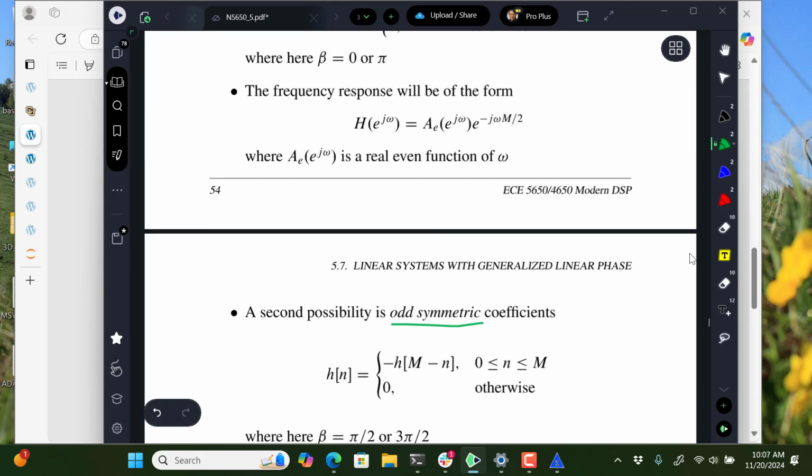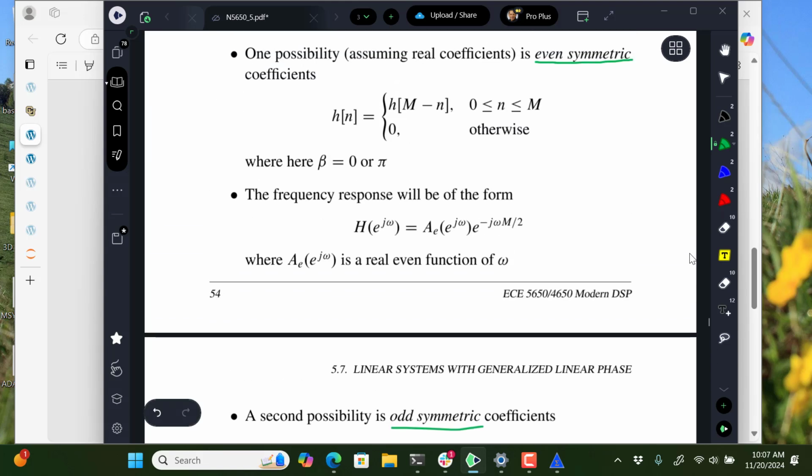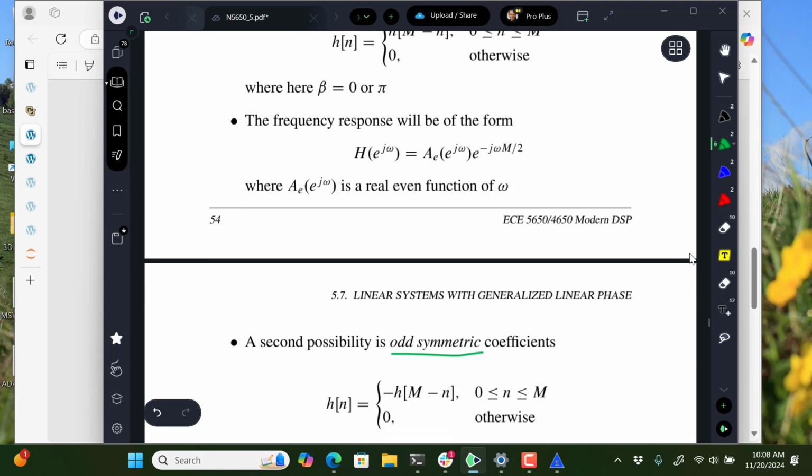So these two equations here say we can show that these are generalized linear phase if you just make a filter that has coefficients that are the same at either end, moving towards the center, that match, and then equal and opposite moving from end to end. So that's the life of simplicity, and that is in essence what the linear phase FIR filter is. If you were to look in any design anywhere, you need to look for symmetry, and that's what people arrived at a long time ago, that this will do it for us.